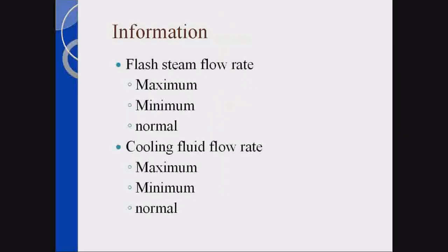The success of the installation is information. The more information you have, the more successful you are. One of the things is that I understand the maximum flow rates. Everyone says, I need the maximum. And that's great, we need that. But the other thing is minimum flow rates. Unfortunately, most of the time we won't get to the maximum flow rate, but 100% of the time we get to the minimum flow rate. And if we don't take that into our calculations to understand that, it can create problems.